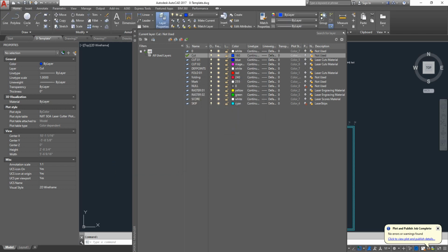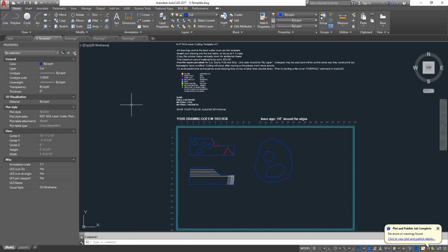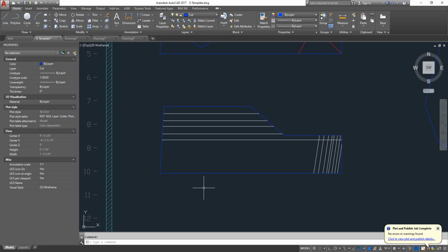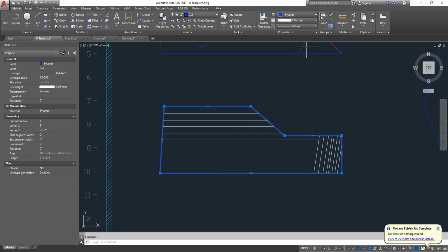So how do we fix this? Well, this is actually where the template comes in incredibly useful. Actually, before we get into that, there's another issue that sometimes happens if you had done your project in Illustrator. The lines will actually come in with a set line thickness. So this looks like a regular 0 thickness line to us humans, but to the machine, it's actually 1.06 millimeters. So this would, especially on the white machine, not cut properly.